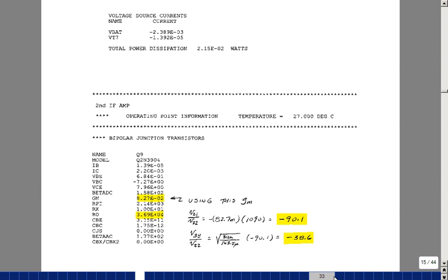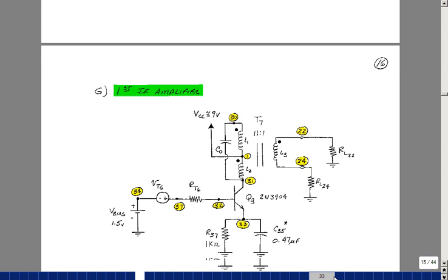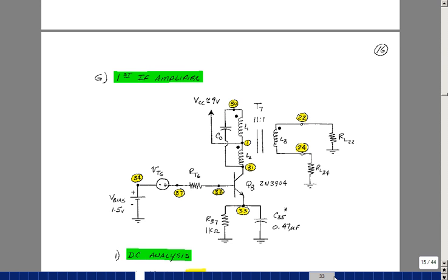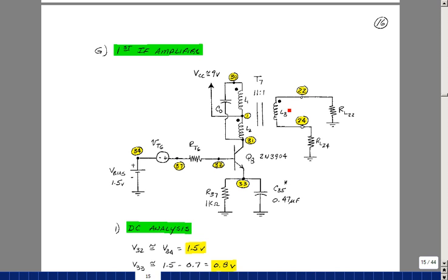Part of the transformer is only being used. It's really the center tap to one of the ends. The stage that's feeding the second IF amplifier, again this was a bandpass filter, is another bandpass filter, so we're getting like a doubling effect. And so again, what this transformer is doing is that these two coils are giving us the voltage gain for the transformer, and then effectively a reflected load here and a breaking up of this capacitance as some parallel equivalent circuit. So when you're tuning the transformer, you're adjusting the value of L. The value of C is just fixed there. You're able to tune it to a particular frequency, in our case 455 kilohertz for the AM radio.